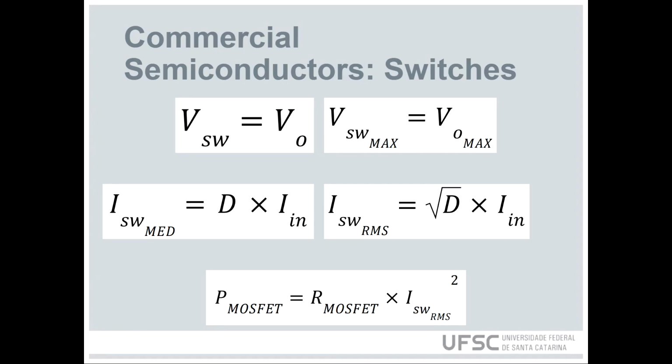For the choice of switch, we calculated the maximum average current and the maximum voltage, and we made them a prerequisite. We reached the option of two switches, MOSFET and IGBT. Opting also for a high switching speed, which is beneficial for choosing better capacitors and inductors, we opted for MOSFETs. In the boost converter architecture, we know that the maximum voltage across the switch is equal to the maximum output voltage.